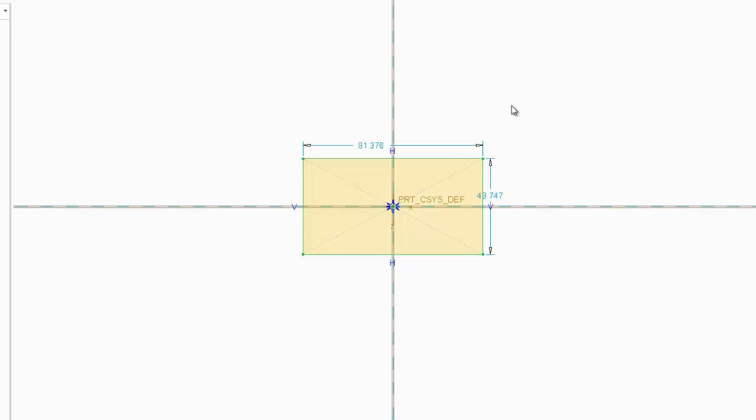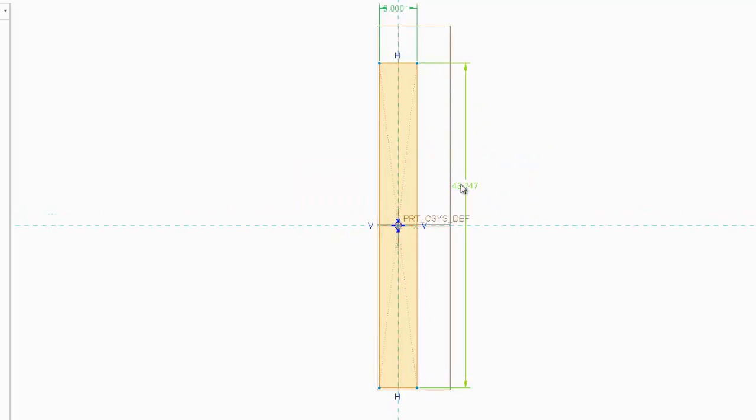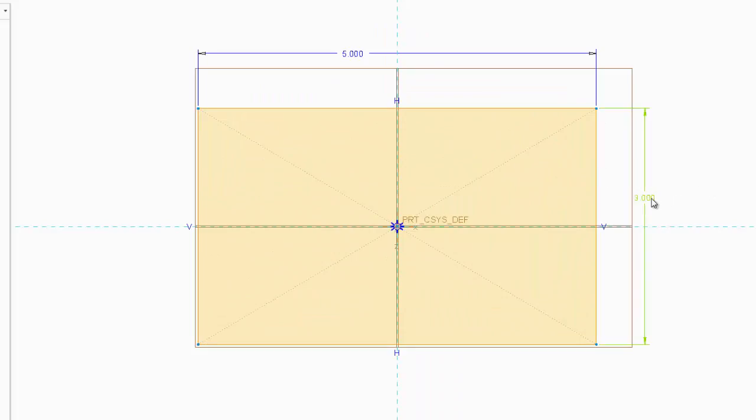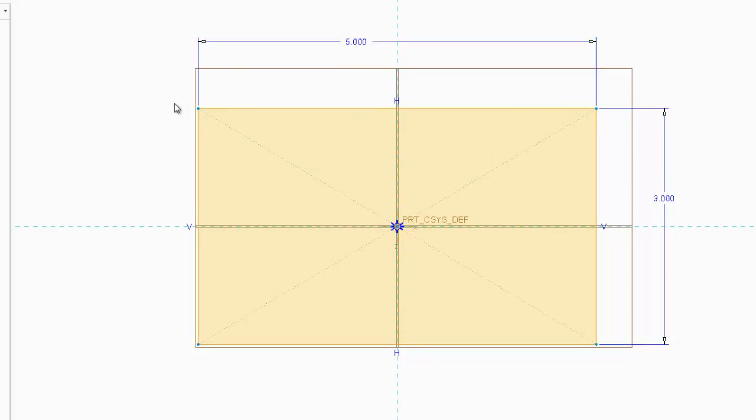And I will go ahead and drop my rectangle in there and middle click. Once I middle click, the solid area inside the shape will shade in the light orange color, and my weak dimensions will automatically come up for me. So once I go in here and change these dimensions to my actual preferred dimensions, they will then become strong dimensions, and I can tell this because the dimensions are a darker shade of blue.